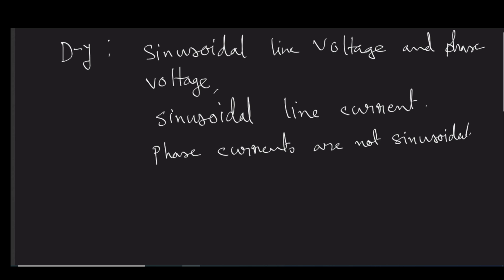Whenever there is a third harmonic current, Ni by reluctance is equal to flux. So if you get third harmonic current and flux, they will also share a linear relationship, because third harmonic current magnitude is very small compared to the fundamental harmonic current. Therefore it will maintain a linear relationship.